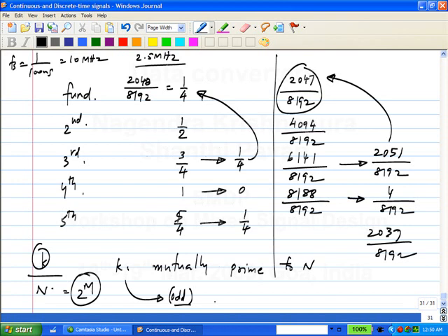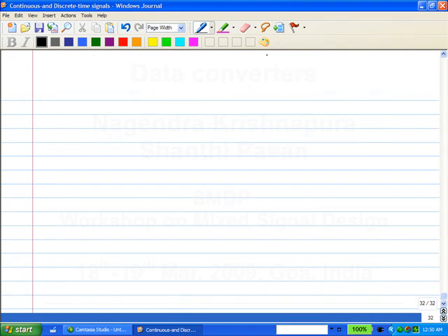So let's say your amplifier has a characteristic 1 times x plus 0.01 times x square plus 0.01 times x cube plus, you can take as many terms as you want, x to the 4 and so on. And you take x to be a sine wave as before.